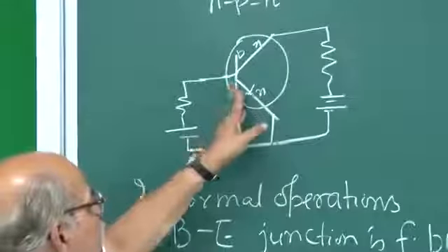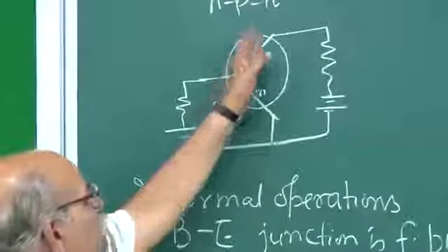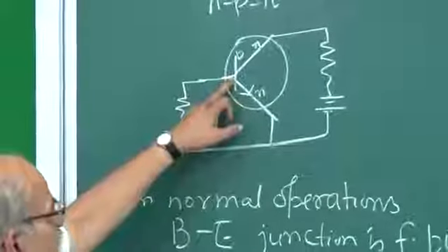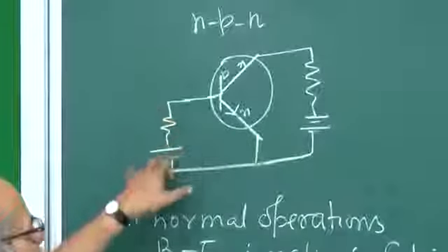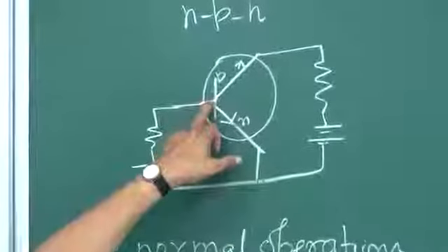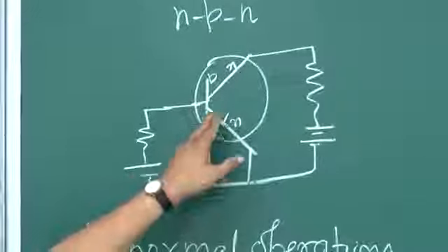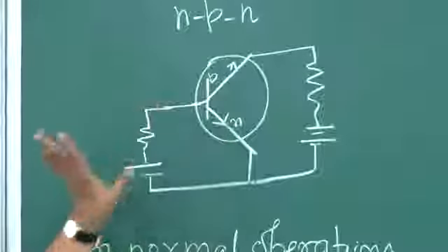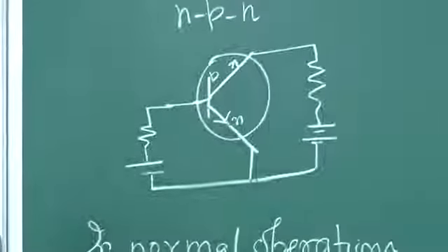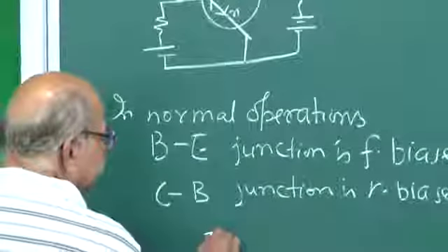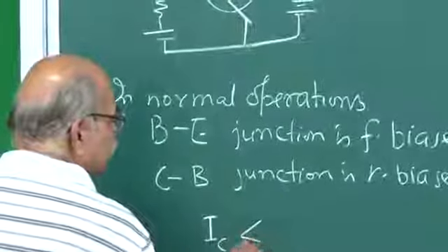So, a lot of electrons go through this collector circuit, and some small fraction goes through this, and that corresponds to the recombination of holes and electrons once these electrons find themselves in this P region. So, this was the mechanism, and under that you understand that IC is less than but close to IE.